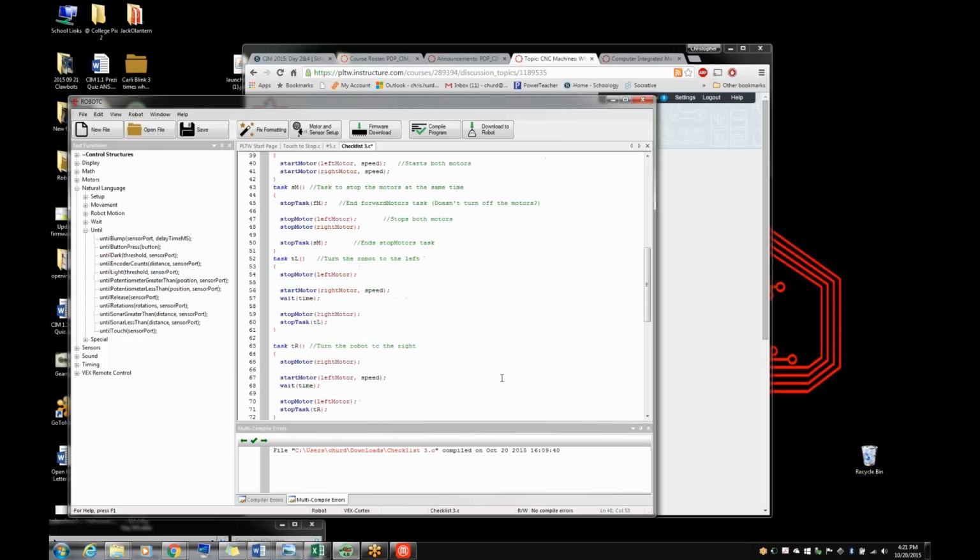The Firefly program was a lot of fun. I only had one group come up with the same solution as me, but it was an interesting little thing, realizing that we could use really, really short waits in a count to basically have the thing spin in a circle, and ultimately every 10 microseconds check the light sensor value, then run the motor for 10 microseconds, then check it again, and then run the motors. And when we ran it, all you saw was the thing just do a 360.